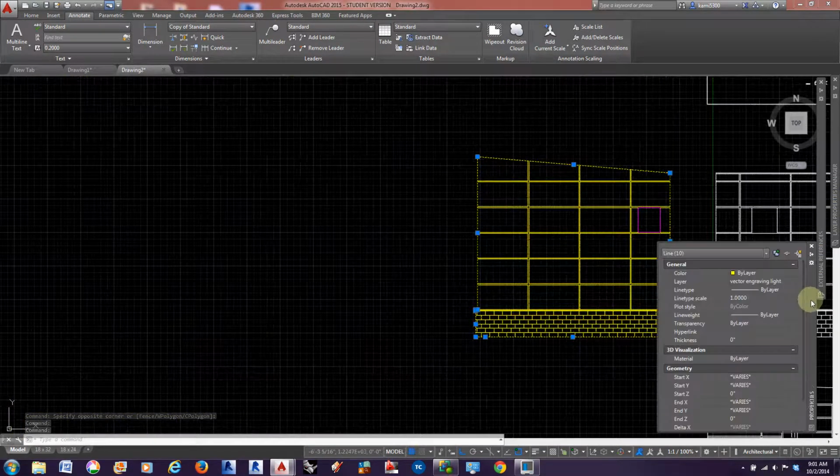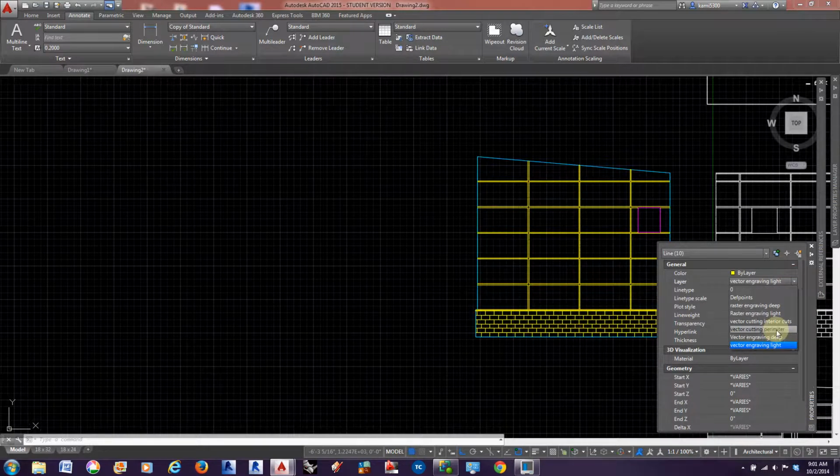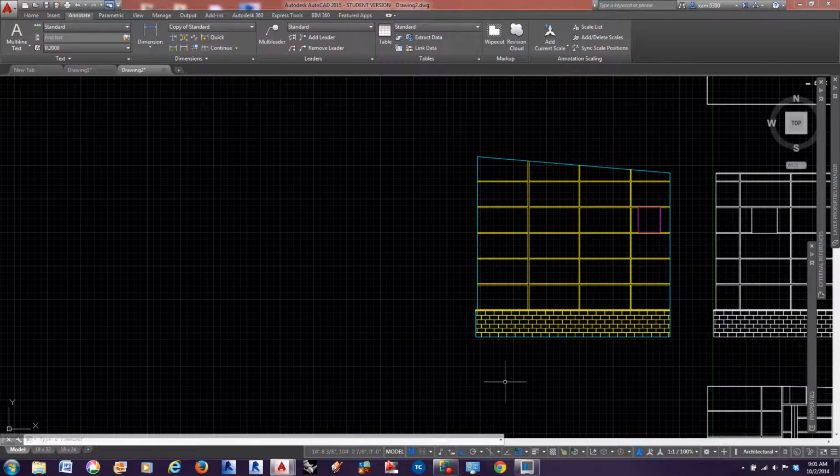And we're going to put these on our exterior cut layer. So the laser cutter will know to engrave this stuff, and then it'll recognize the blue line as being the exterior or perimeter of that object that we want to cut out, and the purple is recognized as an interior cut, which is inside your perimeter cut. So any cuts that happen on the inside of your perimeter cut, you'll want to be the magenta color.